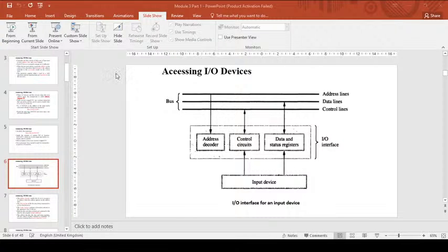So again go back to WAITK and check bit 0 again. Till SIN becomes 1, it will keep going around the wait loop. The program is continuously monitoring bit 0 of the status register, performing no operation.